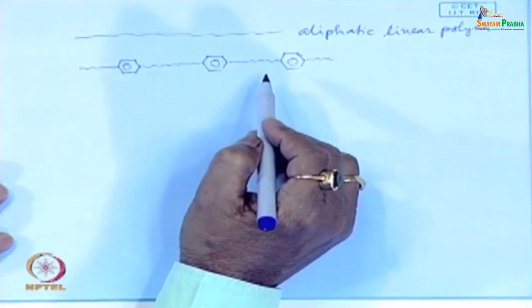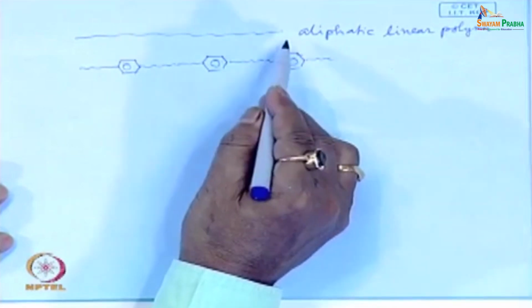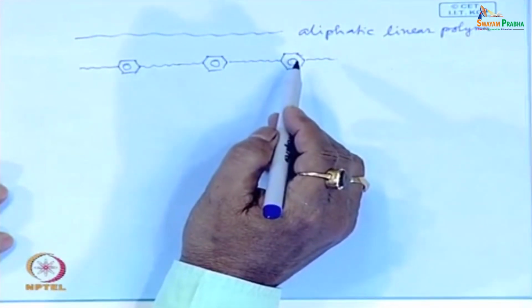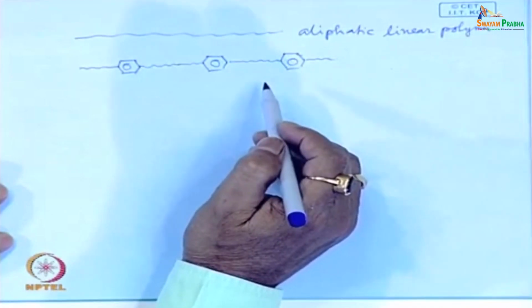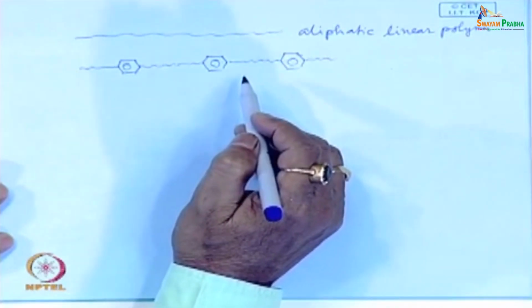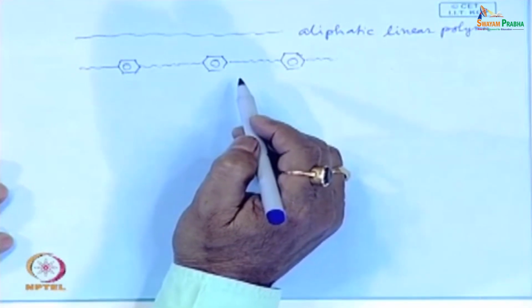But at the same time, if we move like this, we can achieve a polymer with high brittleness. So, you have to think of the impact properties also, you have to keep in mind the impact characteristic also. We need a strong polymer as well as a high impact polymer, as well as a thermally stable polymer, as well as we must see that it becomes easily processable. That means, we have to think of the processability, the temperature at which it melts.